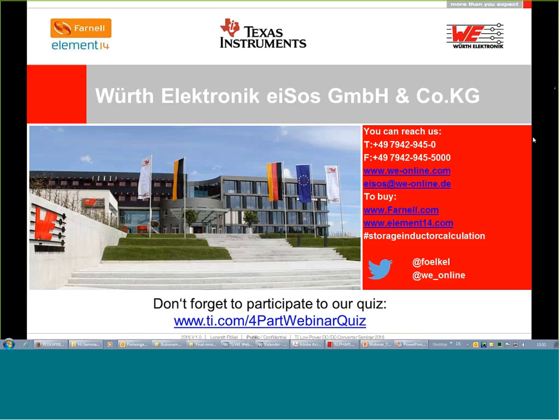Somebody asked if I would use a ferrite bead as an output filter for a buck converter. If yes, would you place more of the output capacitor before and after the ferrite, like a pi configuration? Well, actually, a buck converter has to be filtered on the input. They are very aggressive on the input. A boost converter is more aggressive, more noisy at the output.